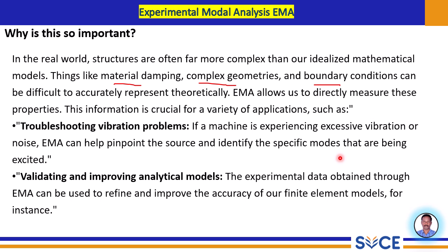Is it a resonance issue? Is a particular component vibrating excessively? Experimental modal analysis provides the answers needed to develop effective solutions such as structural modification, isolation techniques, or changes in operating speed. Then there is the crucial aspect of validating and improving our analytical models, particularly finite element analysis models.